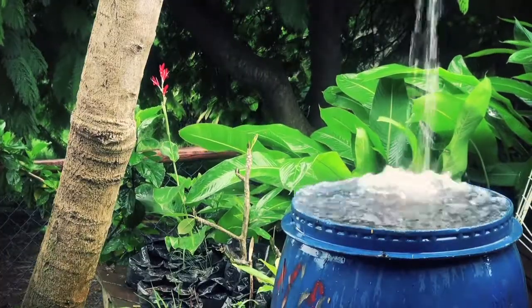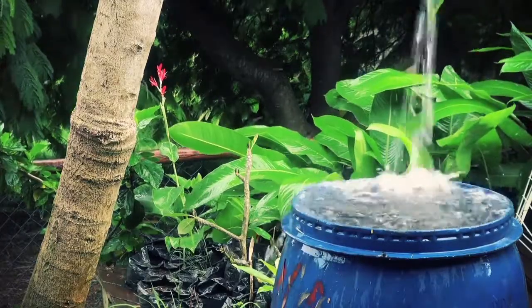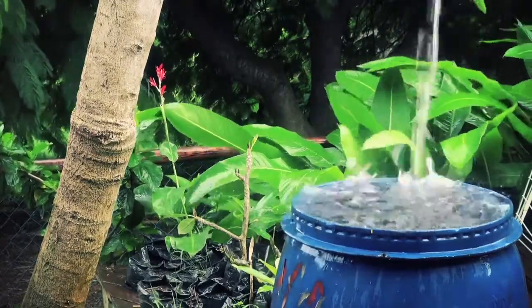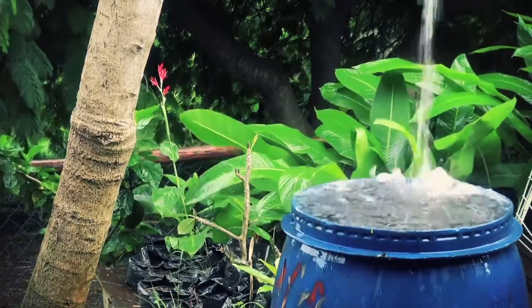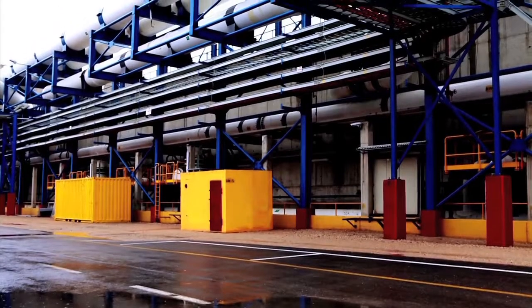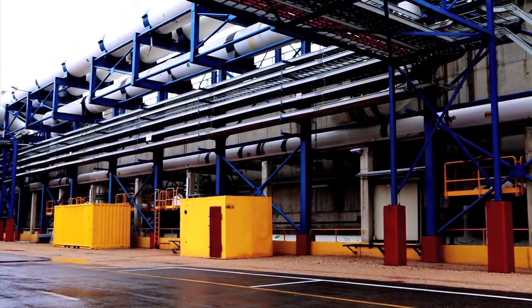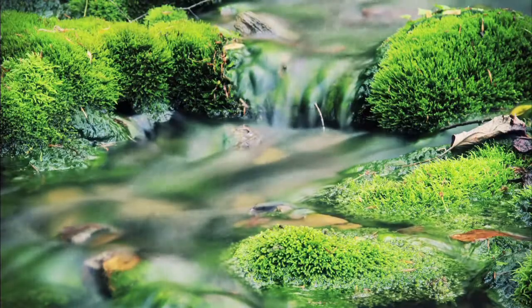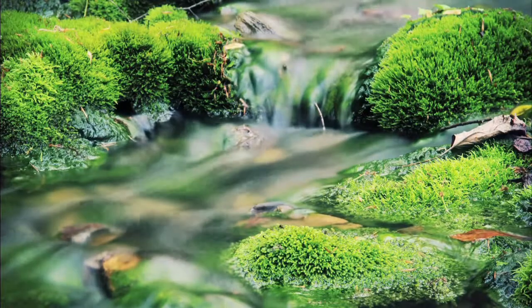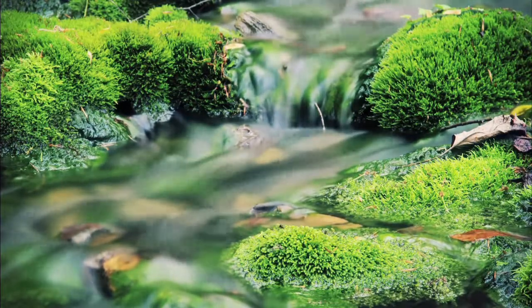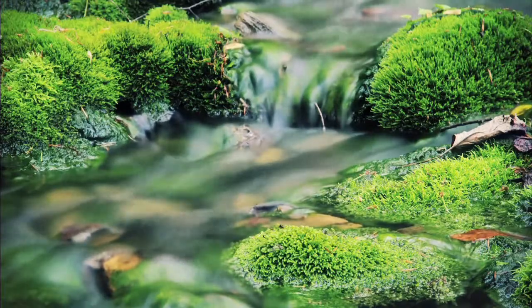Harvesting and reusing rainwater also reduces the need to use potable water for all uses and can reduce both the infrastructure and energy needed to treat and transport both drinking water and stormwater. And finally, we should expect source water protection. Low-impact development rainwater management strategies provide pollutant removal benefits, thereby providing some protection for both groundwater and surface water sources of drinking water. In addition, the approach provides groundwater recharge benefits.